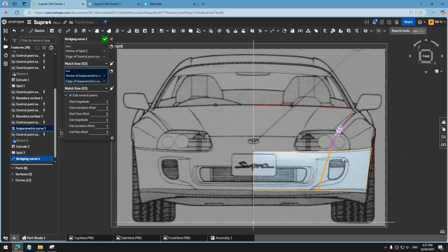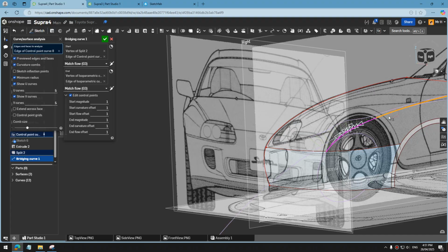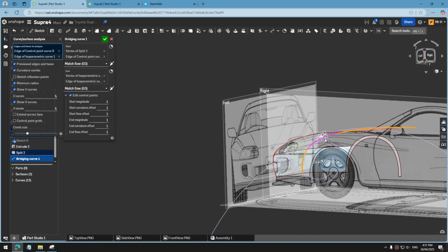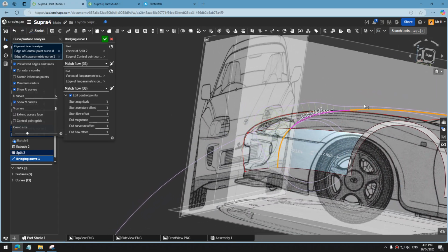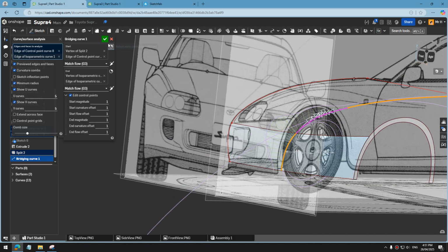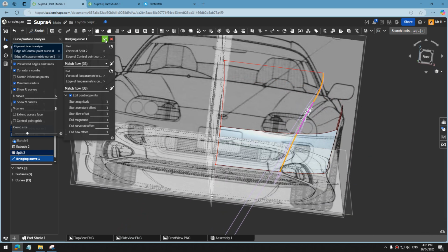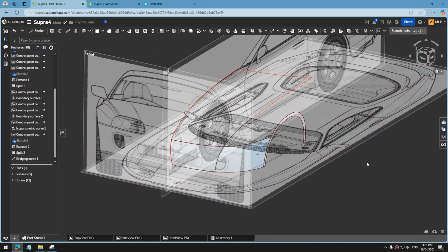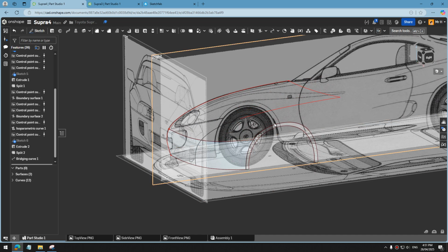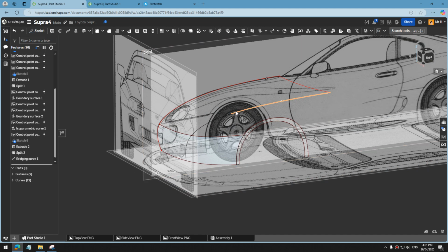If you press Shift C, you can turn on the curvature graphs, and you can see that it's not doing some crazy graphs, it blends smoothly across. So that one turned out actually not bad. So to get a smooth curve connecting to here, we draw a curve down and then we cut it and then blend it between there.